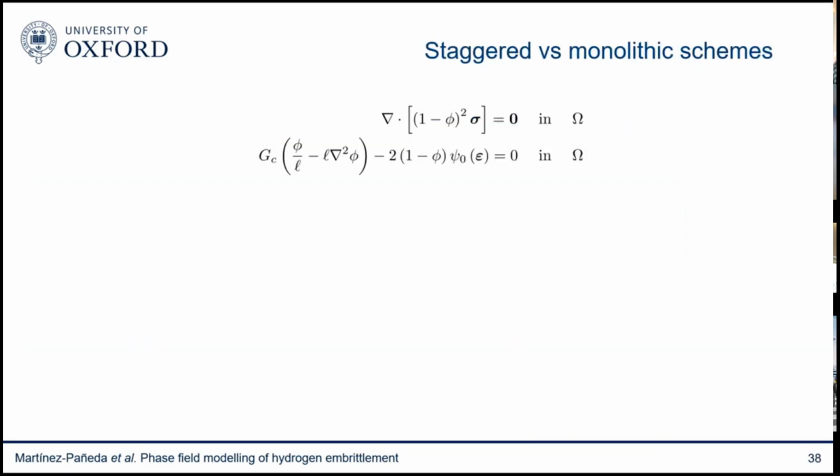So I think the key reason why these are different to other models that I just showed before is this. For example, I was talking before about these ideas of fracture energy and strength. Those ideas are also inbuilt in cohesive zone models. So in a way, it's not that different. Of course, different to cohesive zone models, this allows you to predict cracking in an arbitrary way. So you don't need to know in advance where your crack is going to grow.